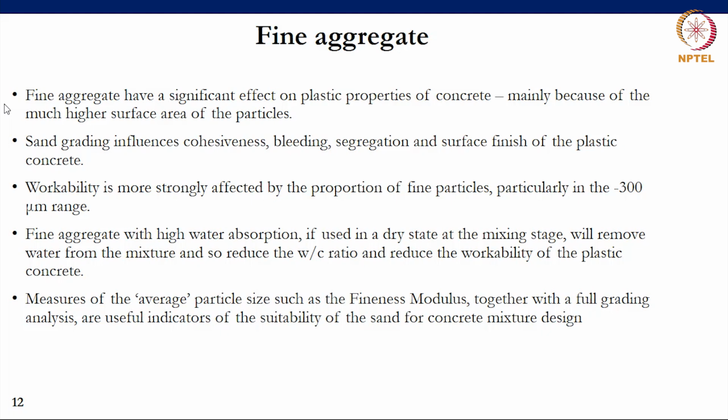Here I'm referring to the ability for the concrete to remain coherent and cohesive when it is moved. A good example is when someone takes a spade full of concrete and then throws it at a distance to another place. Usually the larger aggregate particles will segregate from the finer, more mortar fraction. That refers to the cohesiveness of the material.